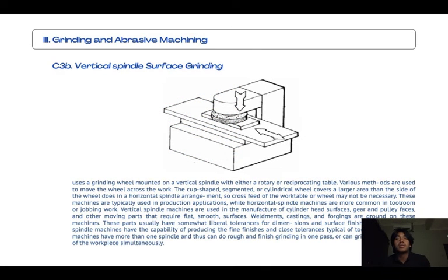Okay, the fifth subtopic is low stress grinding. It's a variation of conventional grinding in which the objective is to minimize stress developed in the workpiece by the grinding operation. It differs from conventional grinding in that very low wheel infeed or downfeed rates are used. Frequently, coarse, softer, open grinding wheels and a liberal flow of coolant are used. Wheel speed also may be low. Abrasive grains in the grinding wheel should be sharp, and wheels should not be allowed to become loaded.